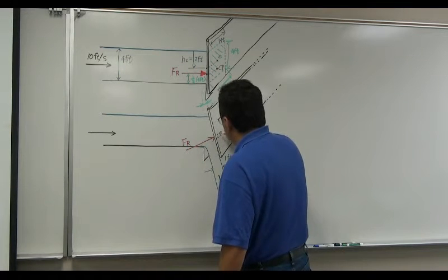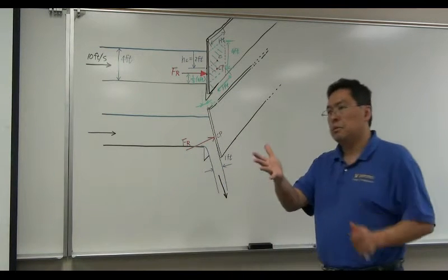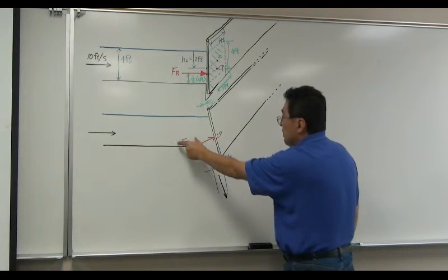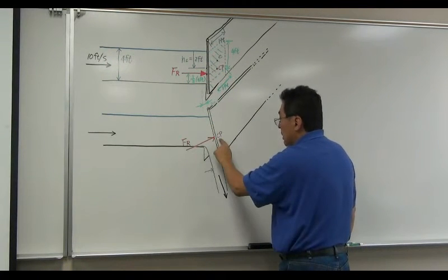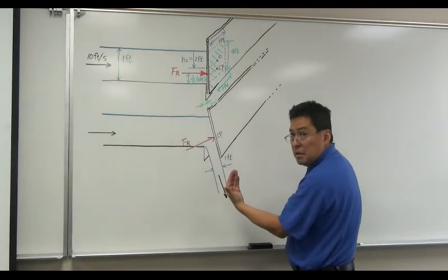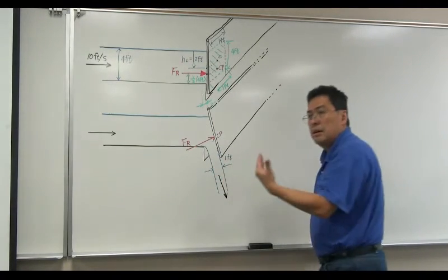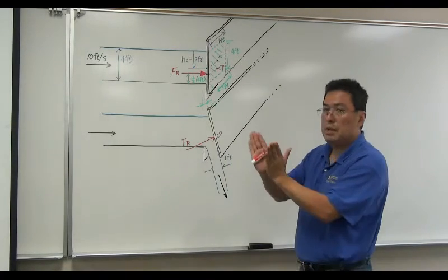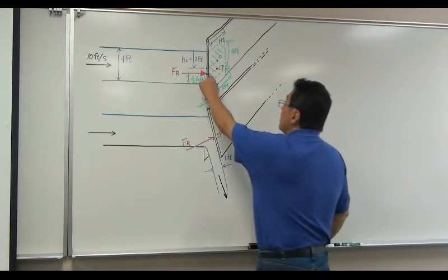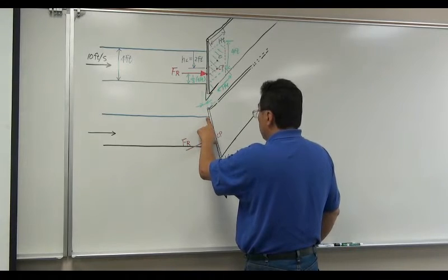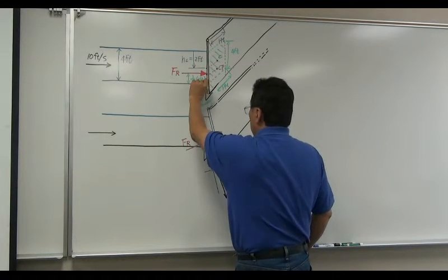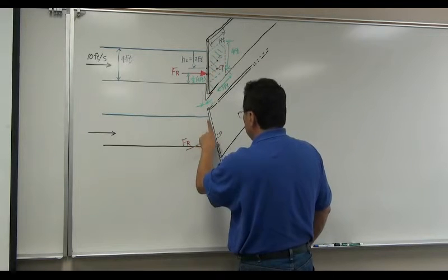Same location of center of pressure, which is probably not true because now this is open with 20 degrees. Maybe this magnitude and location of CP probably changes, but let's not introduce those kind of complications. Let's just simply assume that center of pressure is still 2/3 or 1/3 measured from top or bottom of this cross-section area.